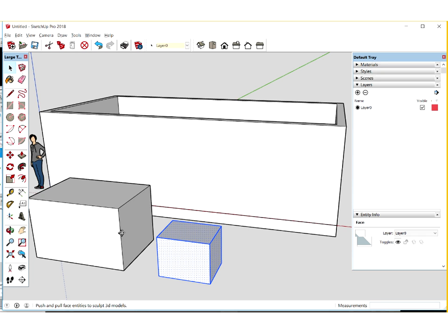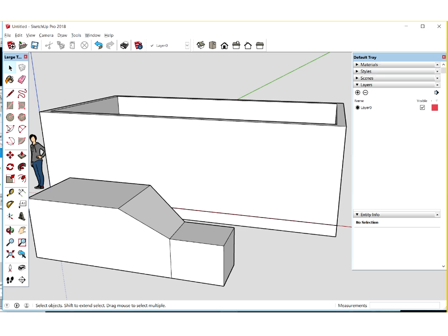Now, if I change my mind, and this can work for you, if you're planning it, this can give you some very good effects, but you'll see that those two objects have become joined. It's called sticky geometry. It is a fundamental principle of the way SketchUp works. So that's why we group things together. Otherwise you'll have chairs that are stuck to your floor and you delete part of them, they leave holes in the floor, all sorts of funny things happen. So groups are the most important thing. First step in organizing your file.